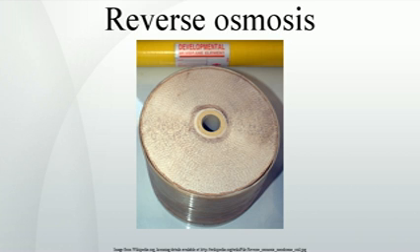High-pressure pump. The high-pressure pump supplies the pressure needed to push water through the membrane, even as the membrane rejects the passage of salt through it. Typical pressures for brackish water range from 225 to 375 psi, 15.5 to 26 bar, or 1.6 to 2.6 MPa. In the case of seawater, they range from 800 to 1180 psi, 55 to 81.5 bar or 6 to 8 MPa. This requires a large amount of energy. Where energy recovery is used, all or part of the high-pressure pump's work is done by the energy recovery device, reducing the system energy input.